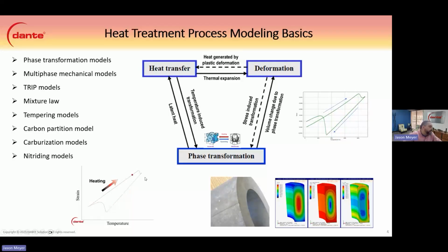At some point with steels, there is a transformation to austenite here, shown by the AC1, and that is the temperature-induced transformation here. And that has a volume shrinkage because it's a little more dense than any of the other phases. And so when it shrinks, you see a little bit of a shrinkage here, and then upon cooling, we also have a thermal shrinkage.